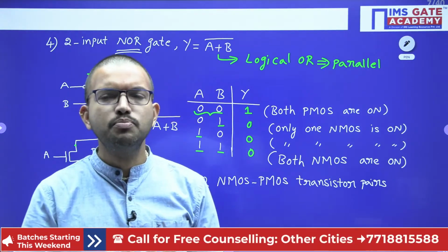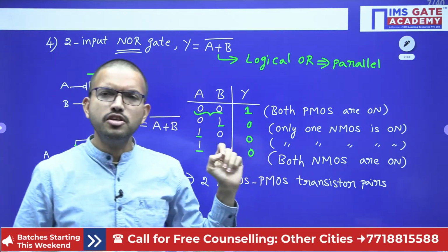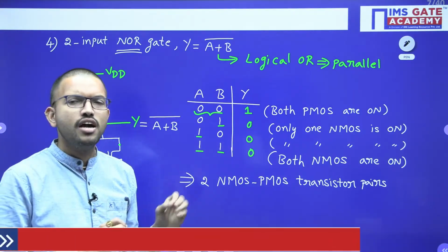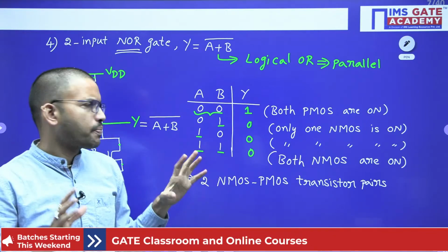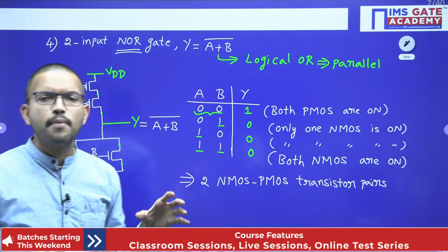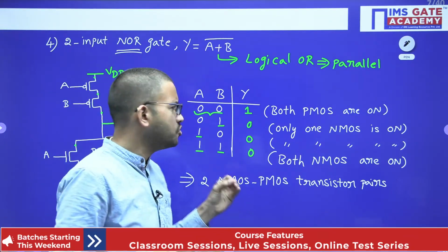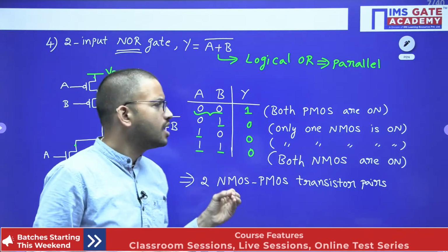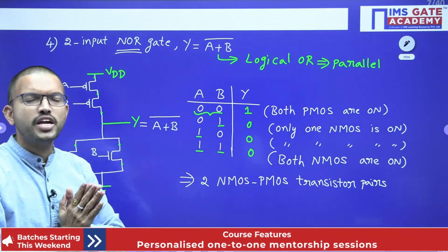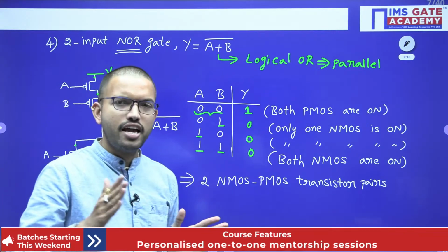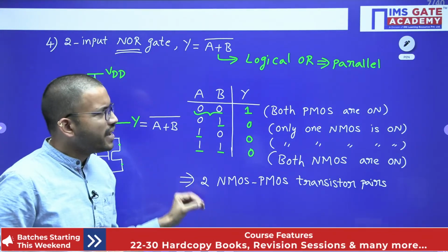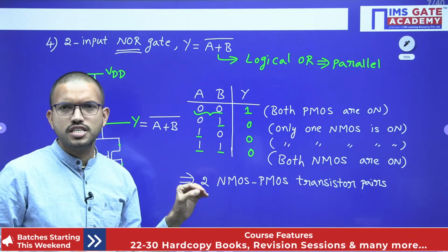That is the beauty, because once you are able to reduce the power dissipation, or the amount of power that is required, even though you are using most of the components present in the given circuit, you can operate the circuit with less power. That means you are increasing the lifetime, right? So this is the main reason why we are focusing on the CMOS logic.